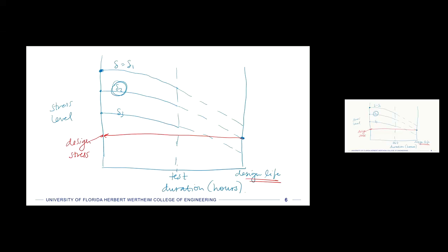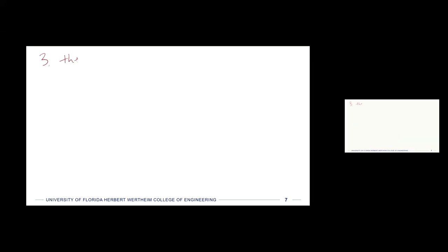And then the third one is a thermal acceleration method, in which case they crank up the temperature and then try to come up with a stress from this. I wrote down that this is also a stress relaxation test. Yes, it must be. Okay. And so this is not an isothermal experiment, but rather the temperature is changing. And it's at super elevated temperatures, but still we want to get out what our design stress is.